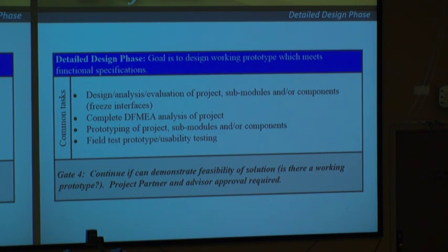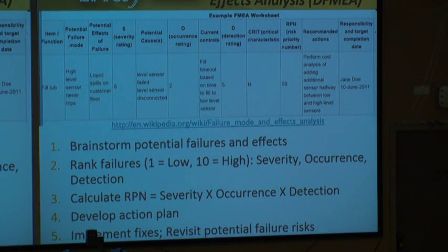Part of this is that you're taking those conceptuals and doing a lot of the more detailed design, as the name implies, to make sure that it's actually feasible, to understand very specifically, for example, maybe current requirements or the overall lifetime, like your battery life, very specific kinds of things that you can start to develop there. So one strategy in this detailed design that applies across is a DFMEA.